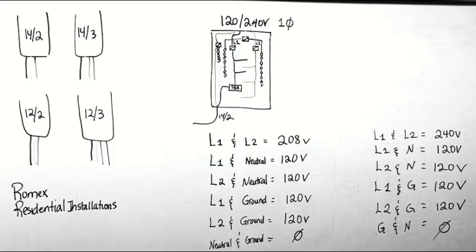So in a parallel circuit, my current does not only have one path to travel, it has multiple paths to travel, depending on how many loads I place. If I have 10 lights, 15 lights, 20 lights in one circuit, let's say for example, a big commercial building, I might put 20 or 30 lamps on one circuit, and then I might put another 20 or 30 lamps on another circuit, depending on how many amps the circuit consumes.